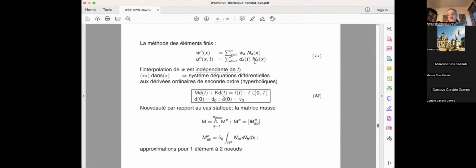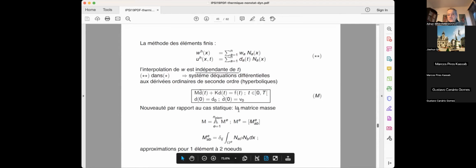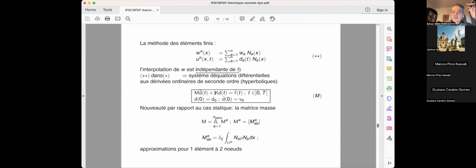So if I go through this development without repeating all the steps, because we have done that already, I will require the derivatives of this to get the corresponding strain approximation. And basically, I'll end up with saying that the given nodal values of the displacement, virtual displacement of three nodes, which are arbitrary, I will obtain a set of these ordinary differential equation in time, where the nodal displacement d of t, second derivative, this is acceleration, is multiplied by a matrix.